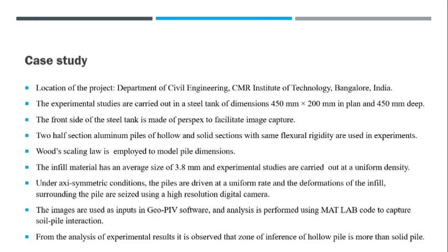The infill material has an average size of 3.8 mm and experimental studies are carried out at a uniform density. Under axisymmetric conditions, the piles are driven at a uniform rate and the deformations of the infill surrounding the pile are captured using a high-resolution digital camera.